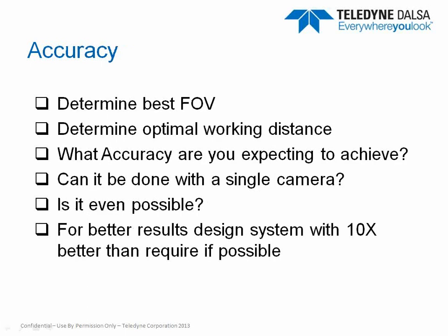If you're doing measurement, the accuracy is best determined by the field of view. So what you want to do is determine an optimal working distance and field of view. For example, if you're looking for a really accurate measurement, you've got to try to narrow the field of view because the smaller the field of view, the higher your accuracy. Yes, you can do it with different types of sensors. You've got a standard VGA 640 by 480 all the way to 12 megapixels, 33 megapixels, whatever you're looking for.